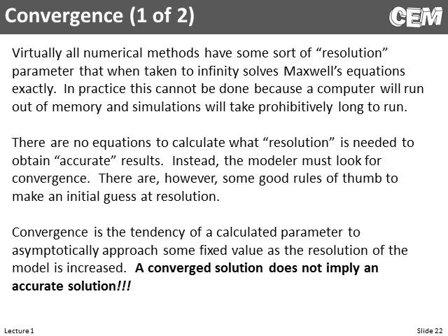So this is really, really important. So we're going to have an array, and we're going to give it, say, 100 points by 100 points. And the question comes up, well, how do I know that's enough points? Clearly, the more points you use, the more accurate your answer, but it's going to slow down. And, well, how many points do you use? I'm going to give you some good rules of thumb on that. But the real answer is you're going to look for something called convergence.